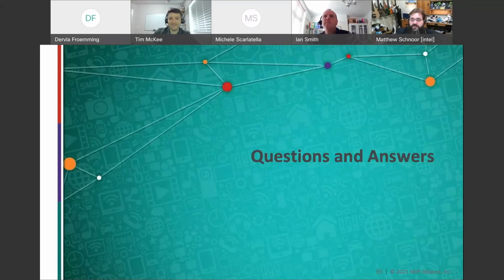It makes sense. I think what we're really getting to is whether your host can handle a NAC as a part of its content protocol, or whether it could see a NAC and say, I'm going to stop processing everything and I need you to deal with this immediately. And what we see different I3C controllers, including host controller interfaces, do is they actually do stop and ask software to deal with that NAC and say, is this something you expected? Should I pick up and carry on? You know, what's the next thing I should do? What's the next command on the bus that I need to issue based on a NAC?